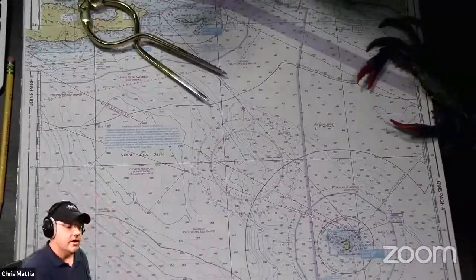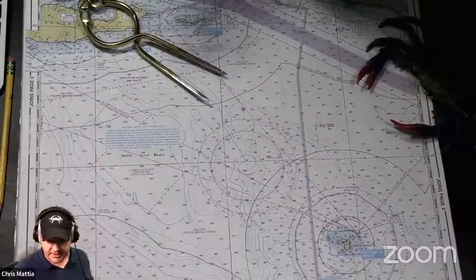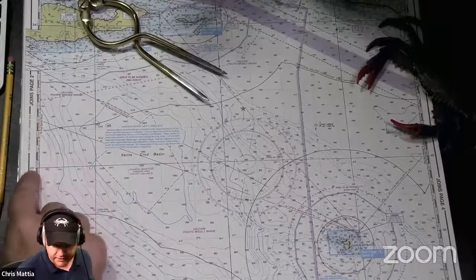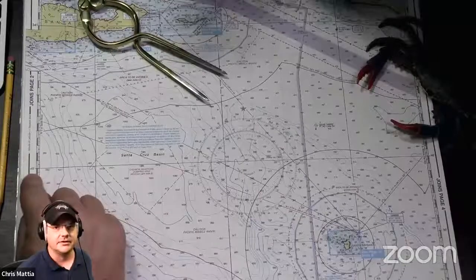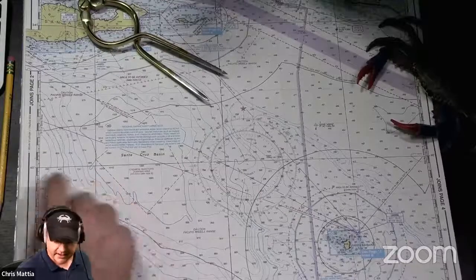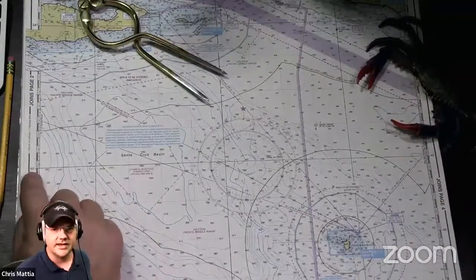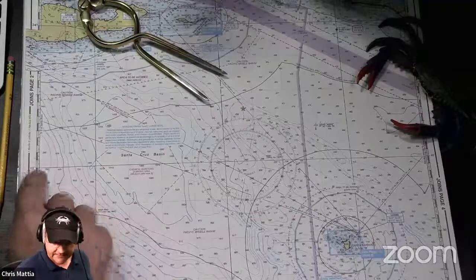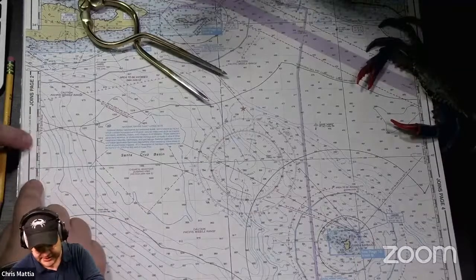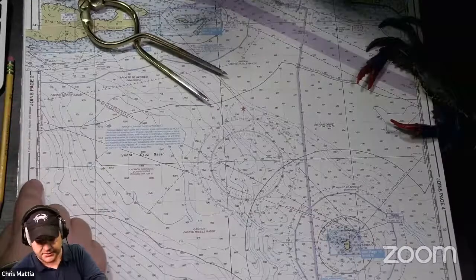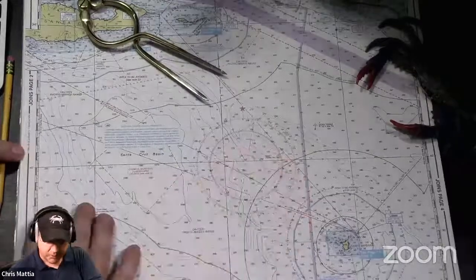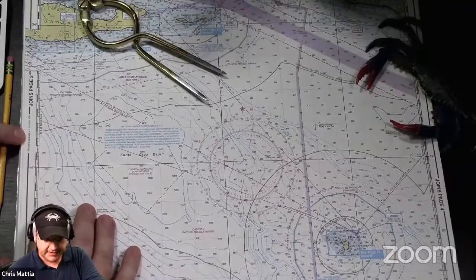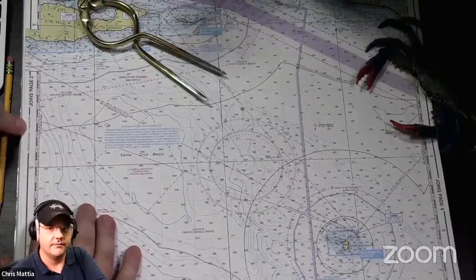Over on the outer edges of pretty much every map, you'll find the lines, and they'll have the numbers on them that tell you your latitude and your longitude lines that are there, the degrees that those lines are on. We're going to talk about that in a second. And then you'll see these different divisions that are set up in here, and each map is going to have some sort of scale. Now, on a nautical chart, 1 minute of latitude is equal to 1 nautical mile.